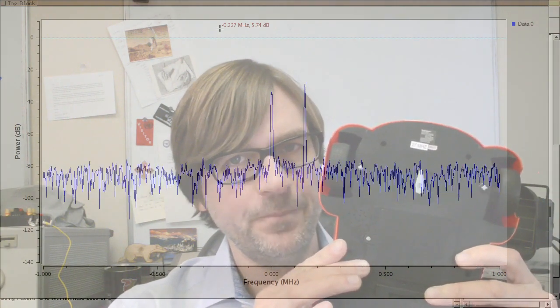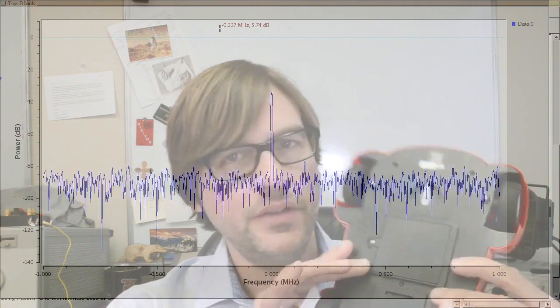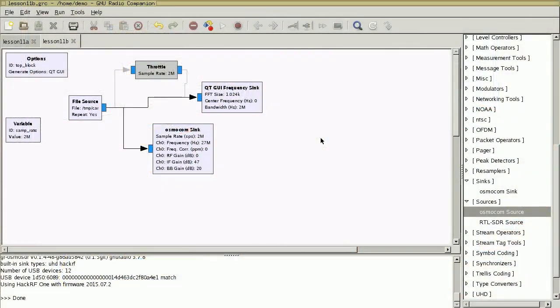The signal's transmitting, and yet still the car's wheels aren't moving. Let's investigate what's going on a little bit more closely. One of the benefits of having a saved waveform like this is that we have a consistent test vector. I'm not recapturing the original transmitter every time I run a flow graph and possibly introducing different problems depending on how I'm holding things or different changes in my environment like interference. Everything should be the same every time I read data out of this waveform.